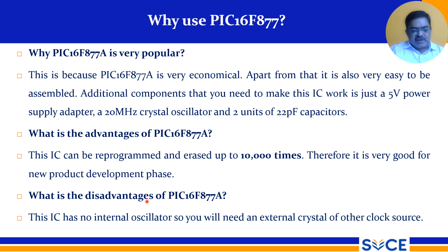And what is the disadvantage of PIC 16F877A? This IC has no internal oscillator. So it does not have an internal frequency generator. You have to connect an external crystal or other clock sources. So that is the drawback here.